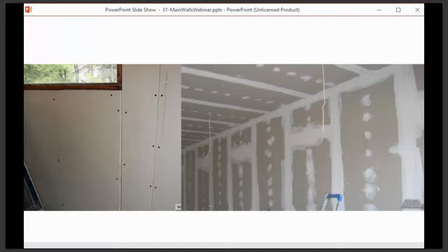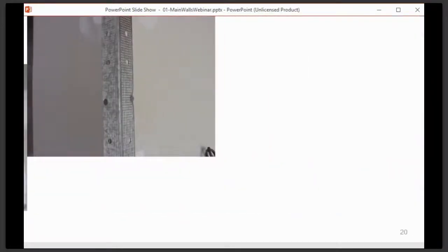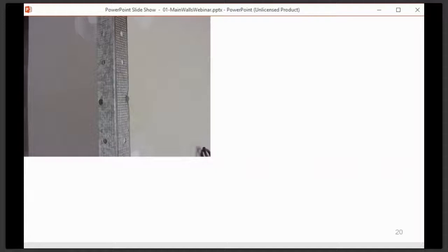Total thickness of plasterboard walls, usually internal walls, is about 100 mils. Okay, it's 100 mils in total. That's the thickness of the stud wall with the plasterboards on either side as well. As a general rule, exterior walls are usually 300 mils, and internal walls are 100 mils.